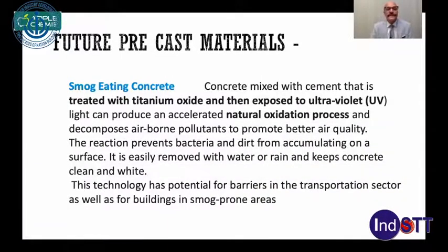In the future, precast material that is likely to come up is smog eating concrete, because I know for sure that in every country and every place, the problem of smog and heavy pollution is there. These are special materials in precast, where the concrete is treated with titanium dioxide and exposed to ultraviolet rays, and then it is accelerated with a natural oxidation process, and they eat the polluting elements.